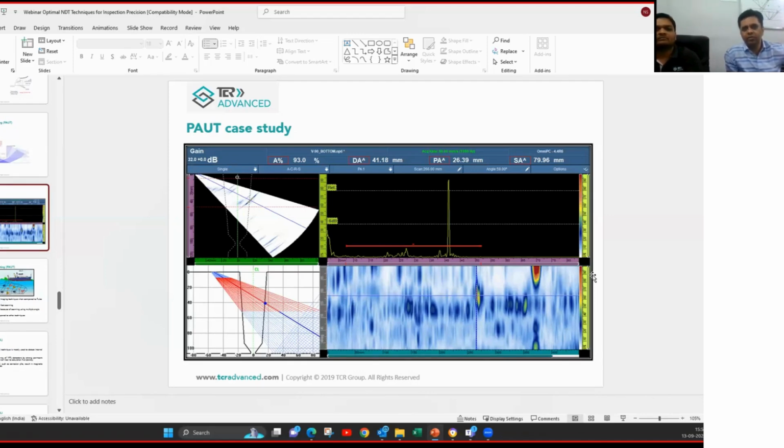Non-intrusive testing like acoustic emission will help in that case to locate where the leaks are. Thermography can't detect anything on the bottom floor. All techniques have limitations, as we understand. Acoustic emission is one that can locate the flaw, non-intrusively.